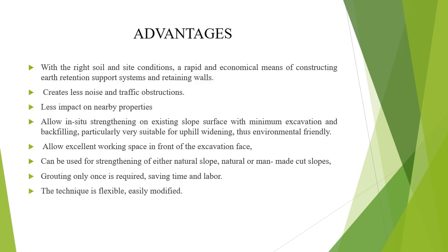Now, let's move to advantages. With the right soil and site conditions, it is a rapid and economical means of constructing earth retention support systems and retaining walls. It creates less noise and traffic obstruction, with less impact on nearby properties. It allows in situ strengthening of existing slope surface with minimum excavation and backfilling, is particularly very suitable for uphill winding roads, and is thus environmentally friendly. It allows excellent working space in front of the excavation face.